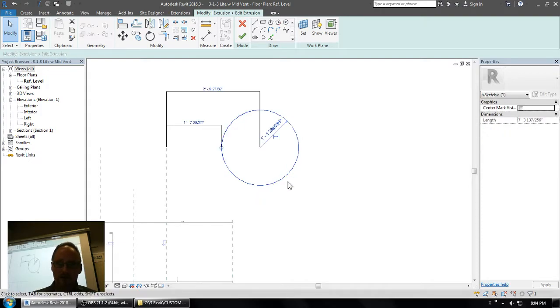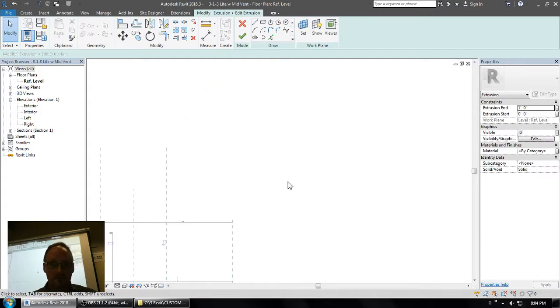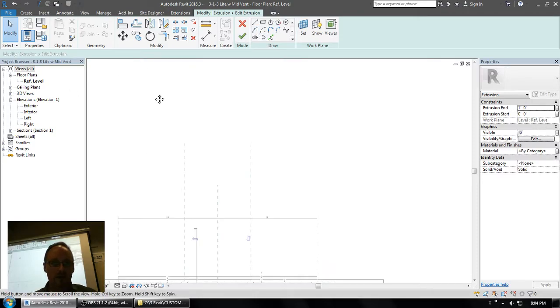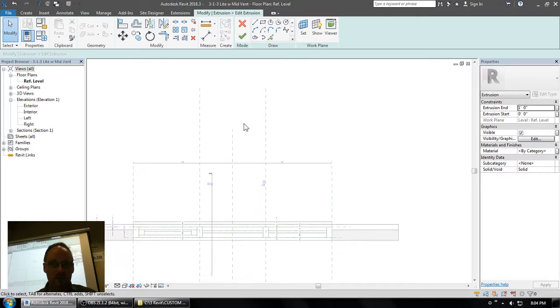Now with an arc, I'm just going to delete the circle here. With an arc, it's actually super easy because the endpoints of the arc are kind of sticky. They will tend to stay stuck to, say, a reference plane that it intersects. So again, I'm in the plan view of this window, and there's these two reference planes here that I'm just going to demonstrate with.